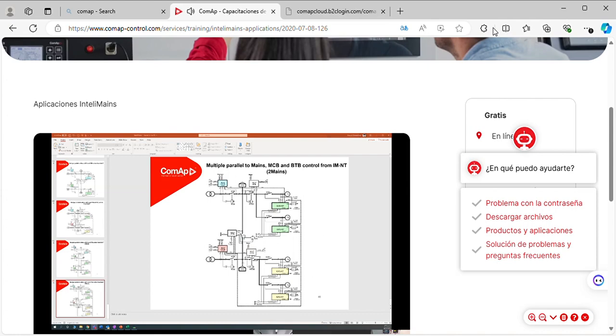So as you can see here, on the top half, I have one utility incoming here, and I have two generators, generator 1 and generator 2. So this is one half, one cluster. Similarly, on the bottom half, I have another utility here, and I have two generators taking care of the load on this half. So for example, here my utility is healthy and it is currently feeding the load. So let me reduce the load here. Okay, so currently it is feeding around 127 kilowatts.